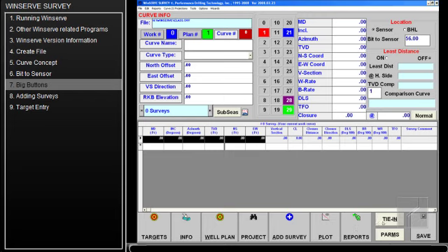This tie-in button allows you to put in tie-in information, and the PARMS button is the one which allows you to set up the method of calculation and the units and a few other things that you need to set up for each survey file. And then the Save button saves the data when you click the button. There's an option where you can set an autosave for every 5 minutes, but generally in this program you click this button and make sure that it's saved.